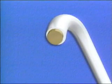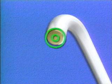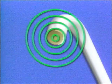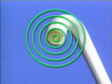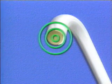There are several factors that affect the amount of inductive reactance. That is, the amount that current flow is limited by inductance in a circuit. For instance, there is a relationship between the strength of the magnetic field cutting across the conductor in a circuit and the amount of inductive reactance in the circuit. So, anything that increases the strength of the magnetic field cutting across the conductor increases the inductive reactance. And anything that decreases the strength of the magnetic field cutting across the conductor decreases the inductive reactance.